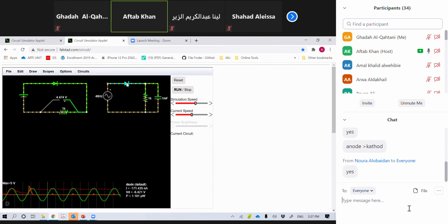And see what is the voltage across this diode. Right click and add to existing. So this yellow orange one is the voltage which is developing across this diode, but the red one is the actual purified DC, and you know DC is a straight line always. So here this capacitor is working as a filter. First this is a rectifier circuit, which is converting AC into pulsating DC. It clips any negative half, only the positive cycle is there. Then the positive cycle which I am getting here passes through a filter, and that filter is basically filtering the output. This is the concept here.